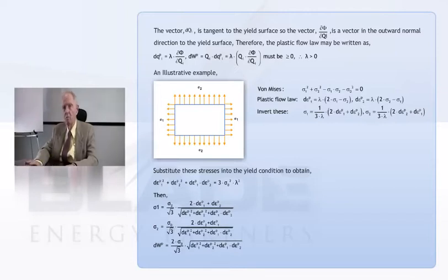And let's say I take this material and I anneal it. Then I could hypothesize that, you notice we have a strain space in that figure above, in the strain space, if I draw my yield surfaces, they'd all be concentric. Then I start to push, and as I push, I drag the first little circle because I hit it first. And then I hit the next one, and the next one, and the next one. And you can actually then, by taking an infinity of these, match any old curve you want.